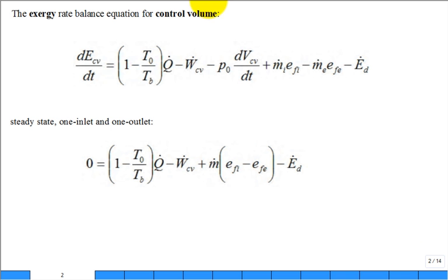So this is our third lecture on Exergy. We've talked about Exergy as a property for a closed system, and also the flow Exergy for an open system. Now you have the Exergy balance equation, just like you have a mass balance, an energy balance, an entropy balance. Now you have a fourth, the Exergy balance. You can apply it to a closed system or an open system.